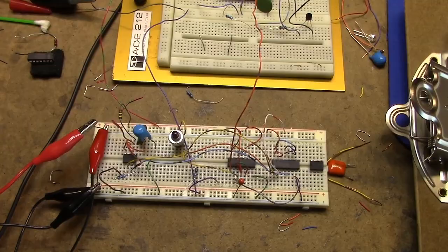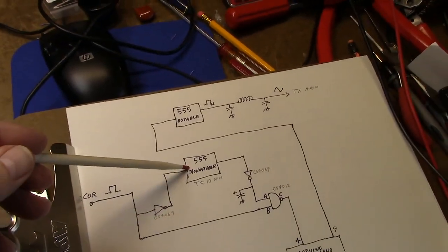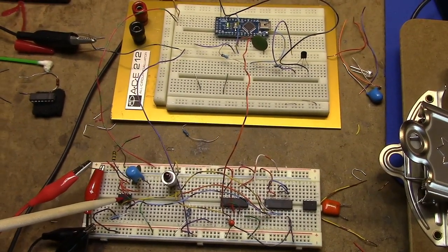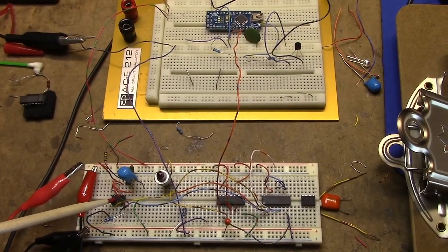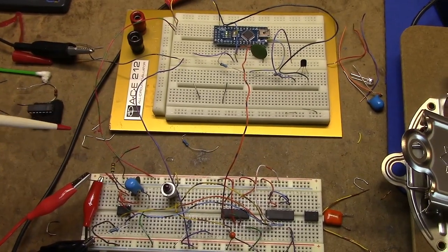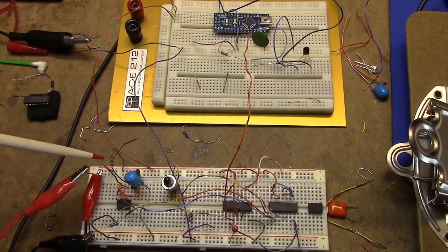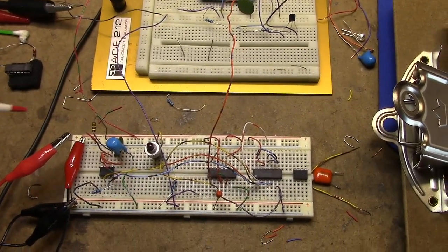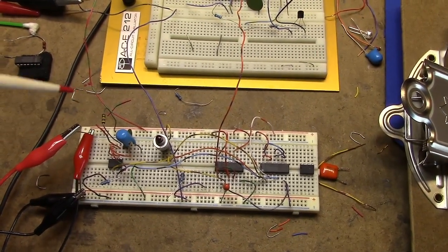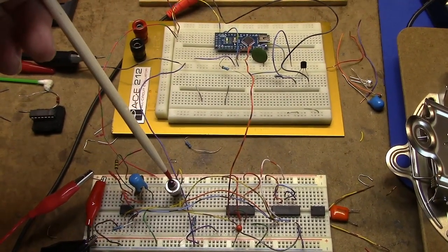And down here on this breadboard I've got this 555, which would be the monostable here, and that's where I generate the timer, which I can set for up to about 10 minutes. I put in a smaller resistor here because I want to demonstrate it, and I don't want to wait 10 minutes to let it time out, so I put in a 100K resistor. This should allow a time of maybe a minute or so, with the capacitor and the resistor I have here. This push button switch here simulates the carrier operated relay in the transmitter.